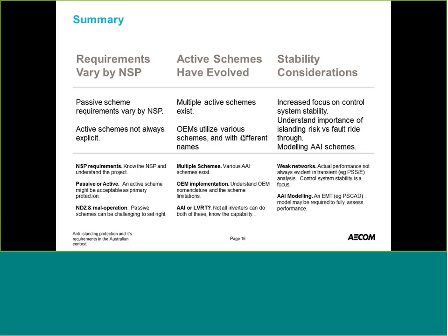Is it the risk of the islanding setup, or is it stability issues where low voltage ride-through is of importance? And lastly, the other area that we're really seeing a bit of development is stability, so stability of control systems, in particular in weak grid networks, where actual performance is not always evident in transient stability studies. So you really need to start with the control system stability, which is one of the issues for weak networks.